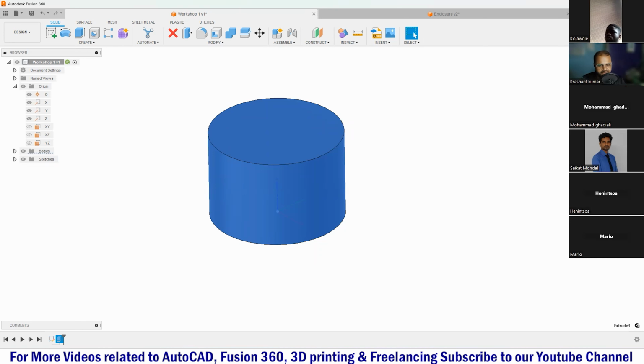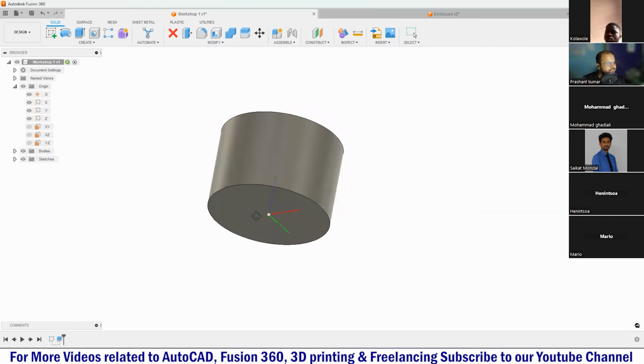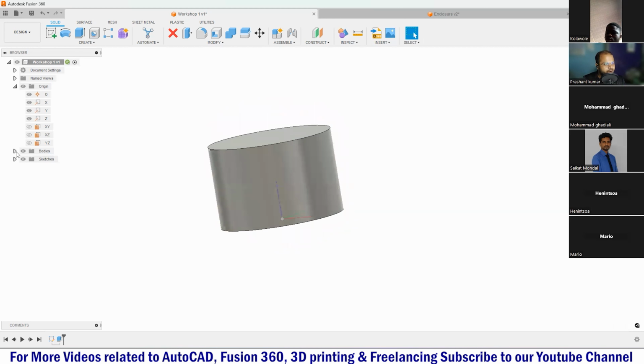Jaya Karyathi is asking, how do you check whether the model created has not moved below the y-axis? Okay, it's a very important question, guys. Whenever you are working inside a 3D model, it's not really important at which level you are creating the 3D model. For example, here you can see, if I turn off the model, one more thing: the moment I created the 3D model, a new folder got created below our origin folder. It's called bodies. Inside that you will be able to see your body.